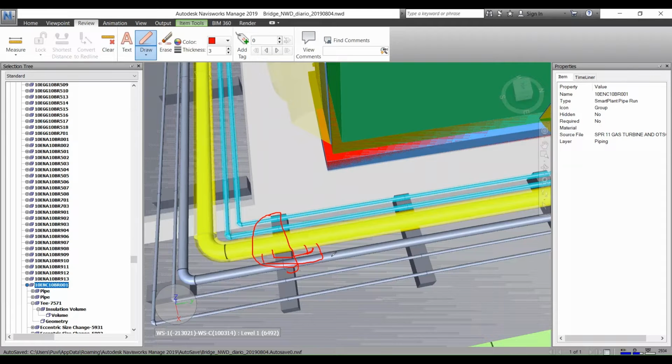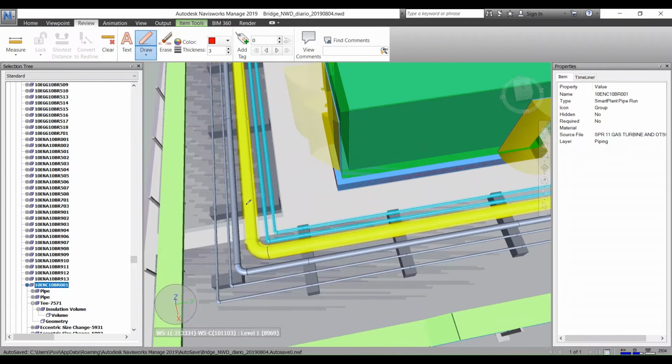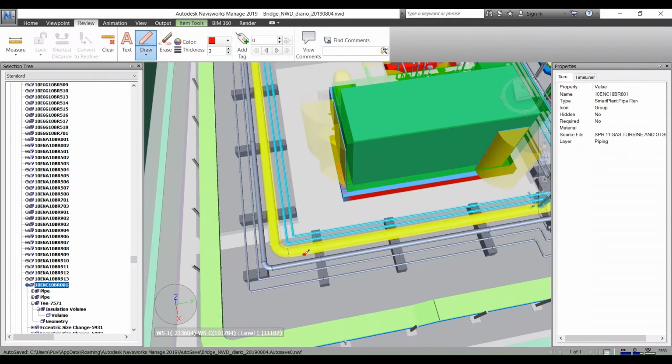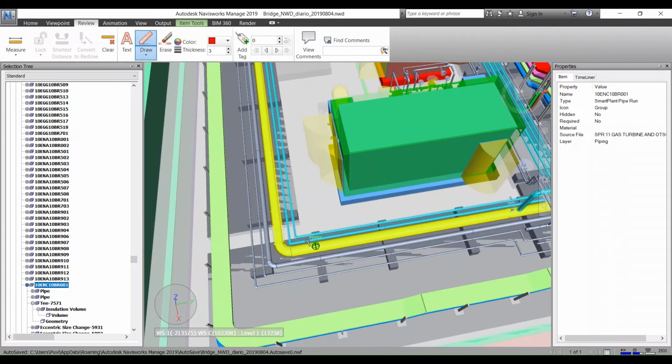So the general standard length is 100 mm. So they will increase by 50 mm, 300 mm, sorry, 300 mm. So 300 mm means they will increase by 350 or 400 or 450 based on the expansion. And also you should not provide any guide here. I told you, in the expansion stresses, because your expansion will be more here. If you arrest this expansion, what happens? There will be a failure at this elbow location, in the expansion case.